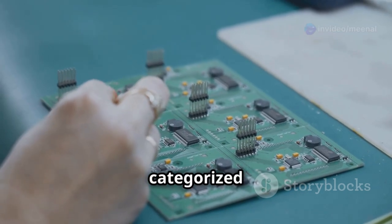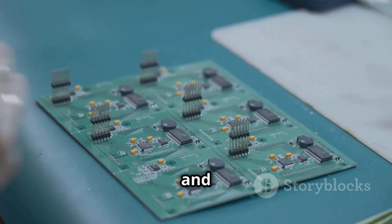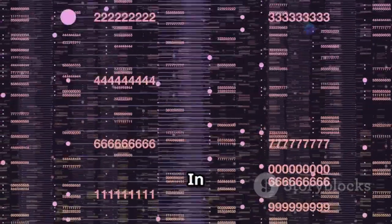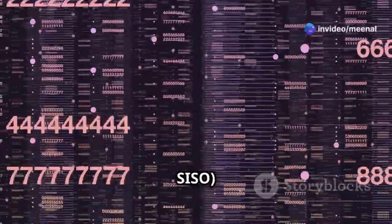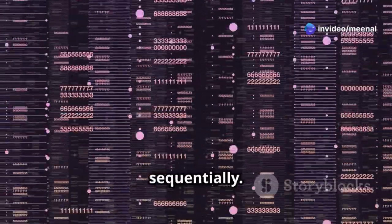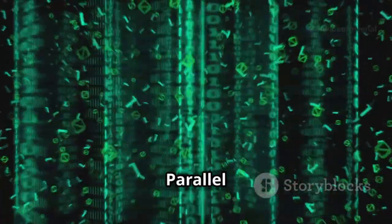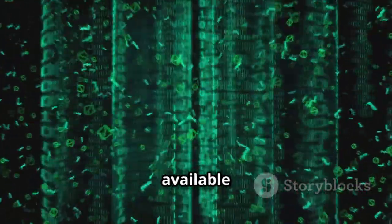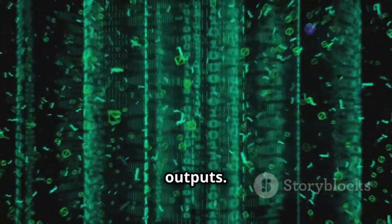Shift registers are categorized based on how data enters and exits the register. The four primary types are serial in, serial out, SISO. Data enters and exits the register one bit at a time, sequentially. Serial in, parallel out, SIPO. Data enters serially but is available simultaneously at parallel outputs.